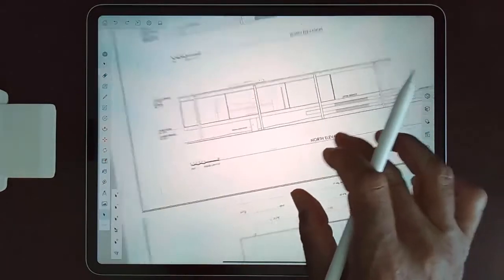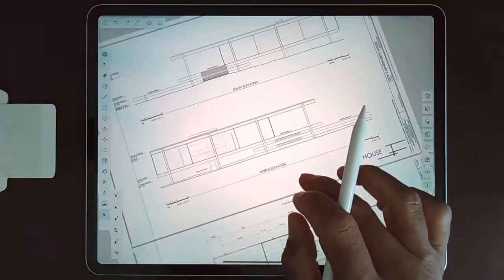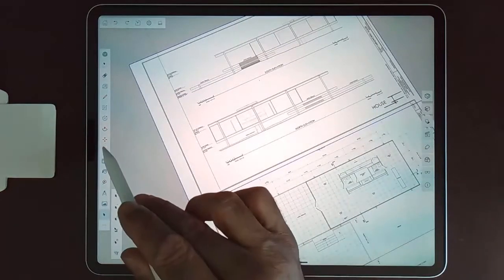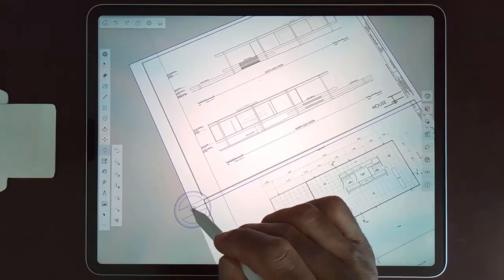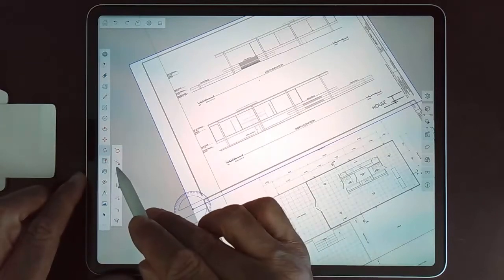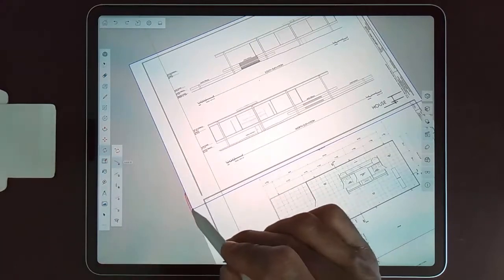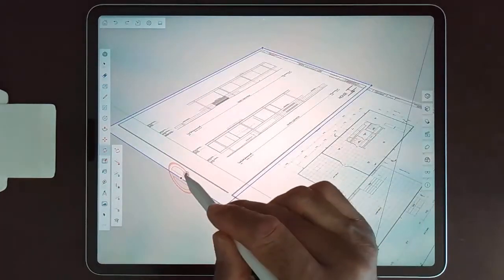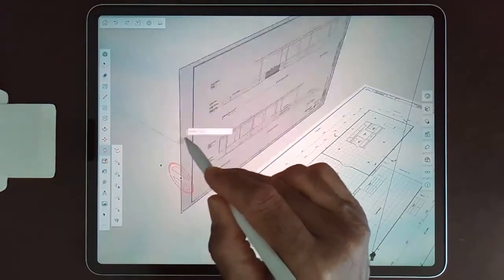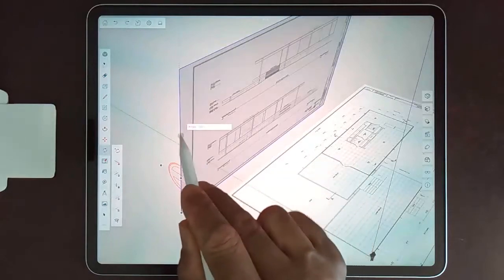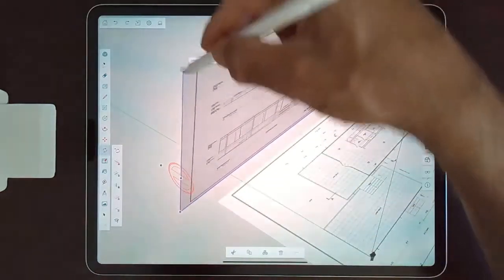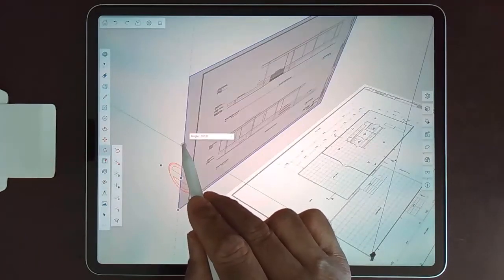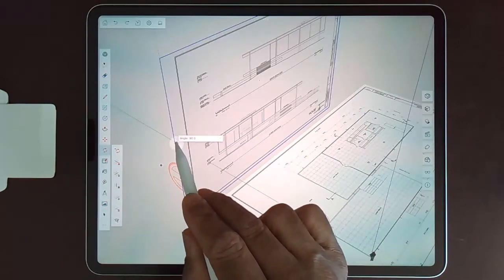So we're going to take this drawing and we're going to perhaps rotate it vertically. So what we're going to do is take our rotate tool, and you can see it's snapping to the z-axis, but we can change that. We can change it to the red axis, and you see the protractor there kind of flip to the red, and we can click for setting the origin, click to set up a reference line, and see the feedback that the app gives you as you rotate around, gives you the angles, and it's snapping in smaller increments.